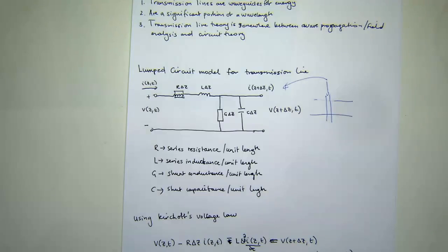So therefore, essentially what happens is whenever you've got a field, whenever you've got current flowing, it usually takes energy in order to be able to change that instantaneous amount of current, and that's what inductance is. Remember that the voltage is L di/dt, which is actually telling you that inductance is a material's opposition to the change in current. Okay, that's where it all comes from. So it makes sense, right?